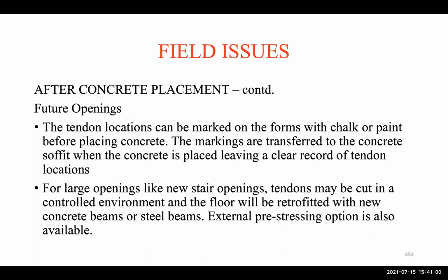So if they cut that opening, then we know that the rebar is there. And of course, they have to know the exact location of the opening and the tendons as well, so they don't cut the tendons, which may lead to a disaster in PT. Okay, and we talked about that.